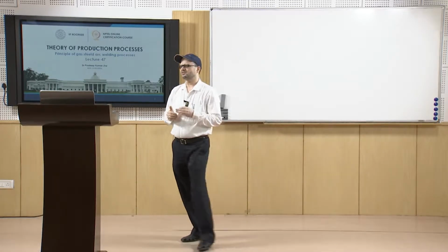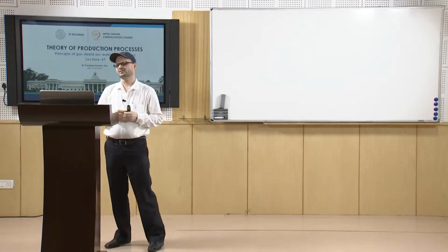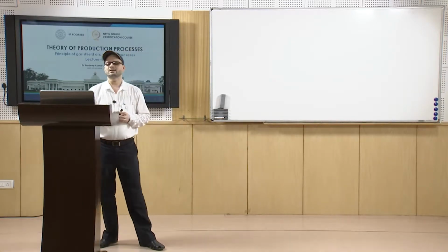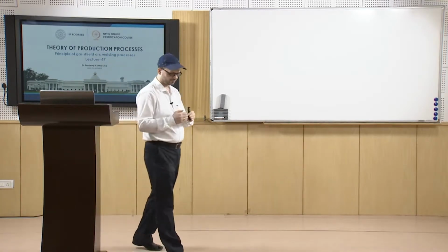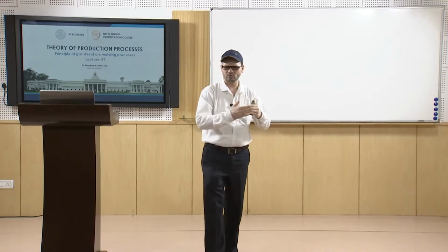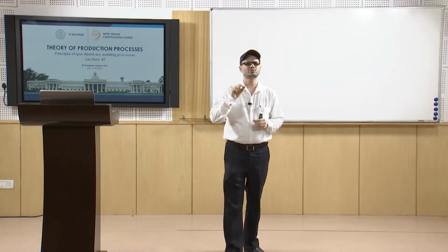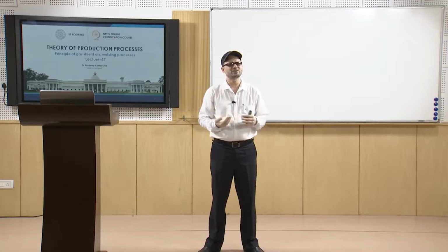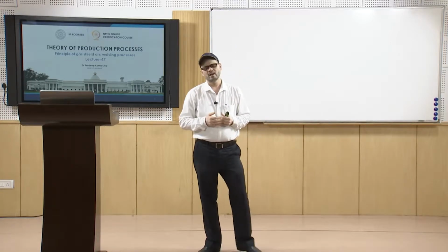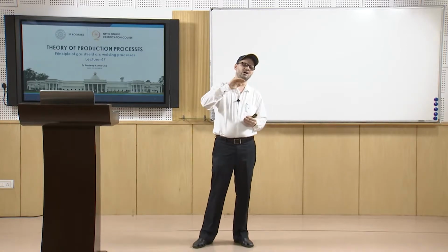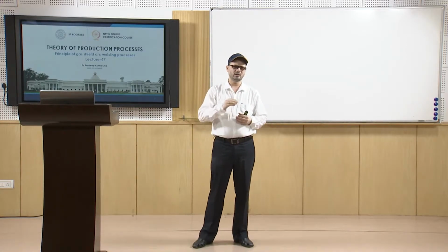The challenge with the shielding in that fashion is that every time you are going for the next pass, the flux is reacting with impurities and forming the slag, which is at the top surface of the bead. That is to be removed every time.